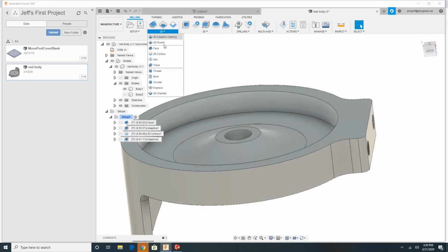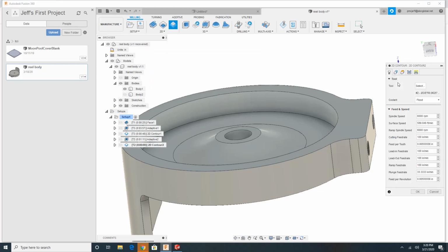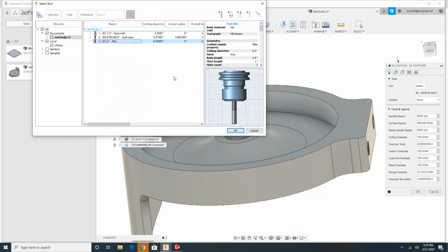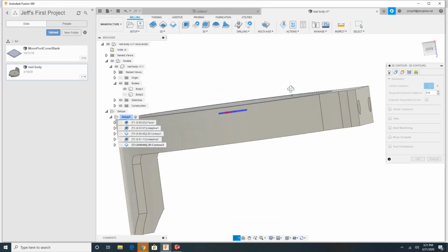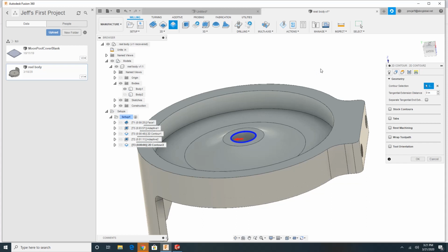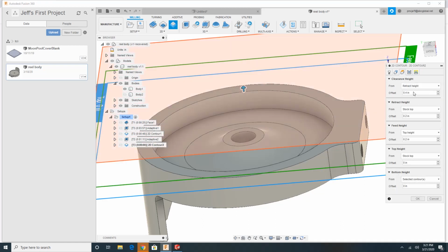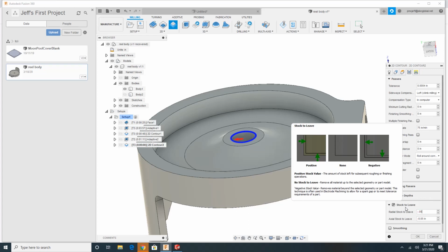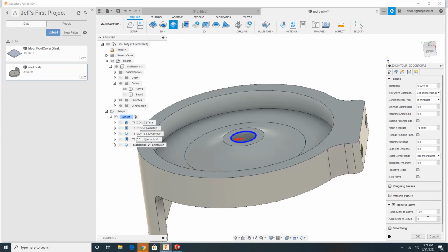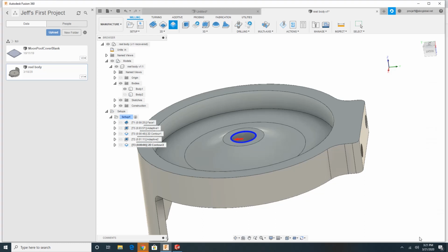So now let's make a contour. Let's go back to our 1/2" end mill. Let's choose that edge. That edge, by the way, is below the surface of the part, so it's not finished with the 1/2" end mill. Or I'm sorry, the facing mill. So I've chosen that edge. What I need to do here is leave a negative radial stock to leave. Negative 50 thou, but not a negative axial thou. We want 0 in the axial thou.